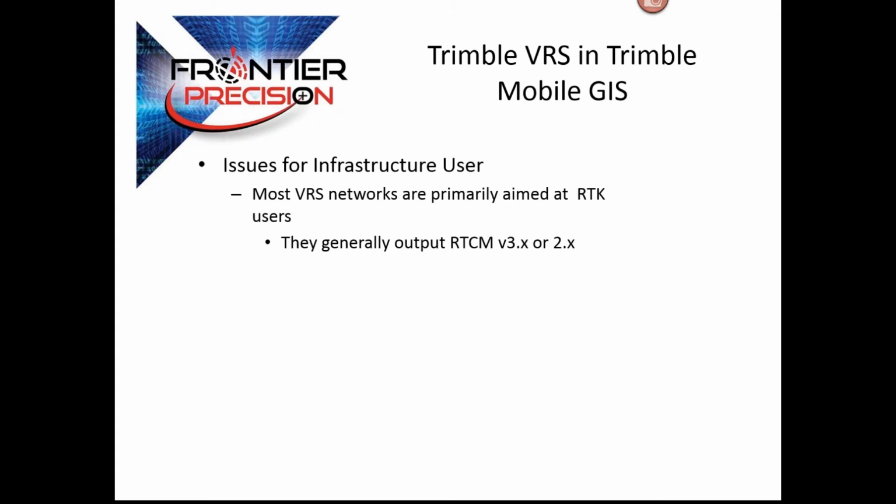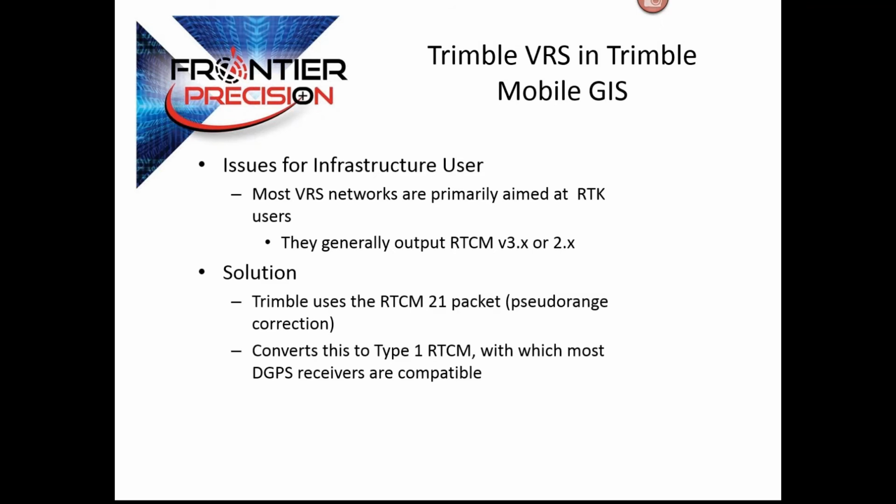But these networks generally output an RTCM 3.x or 2.x, and they can actually have the option to output a DGPS solution, and Trimble can utilize that.